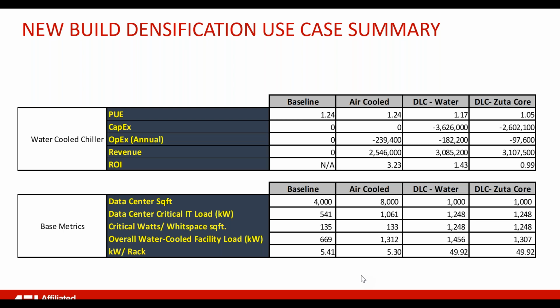Last but not least is a question about covering the heat generated on a server basis. It is more typical than not that 70%, and in some more dense servers up to 80%, and as we saw with chips now going upwards of 400 watts, about 70% and above of the server heat is generated from the CPUs and GPUs. So about 20 to 30% is what's left for the fans to take care of.